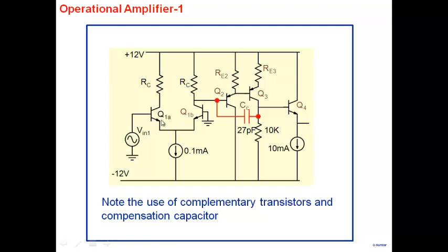And realize here, this is a place where I think some questions were raised. Where do I need a PNP transistor? And we saw that if you use an NPN differential pair, the only way you can add the next stage is through a PNP. An NPN stage did not give us any gain, right? So we saw the necessity of using PNP transistors right here. Okay. So if this is NPN, this has to be PNP. On the other hand, if this were PNP, then these would have been NPN. Without that, you can't connect.